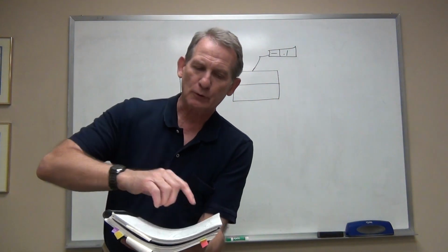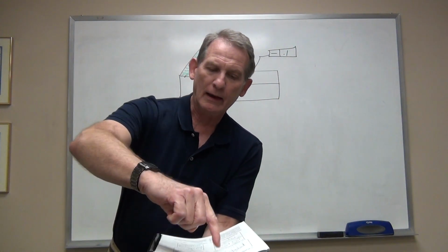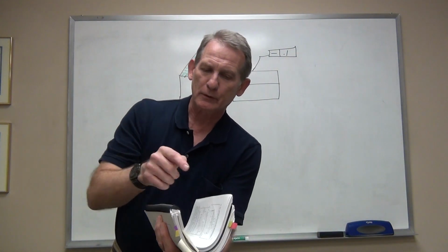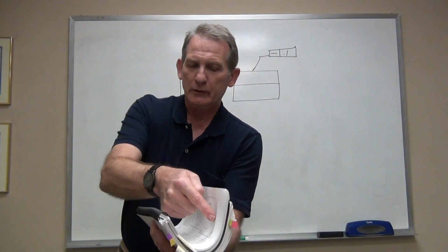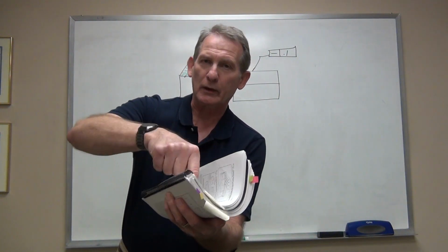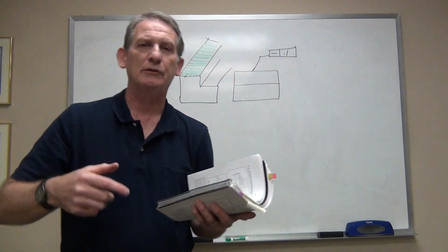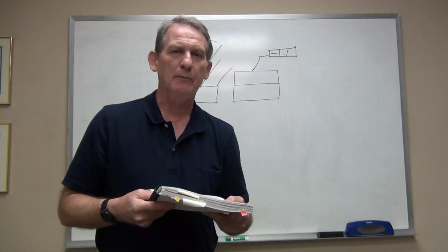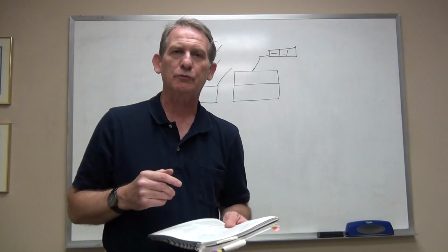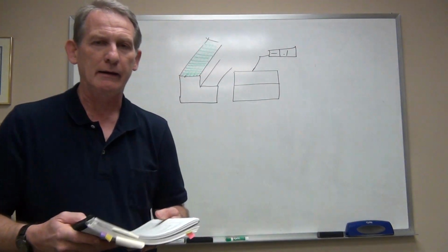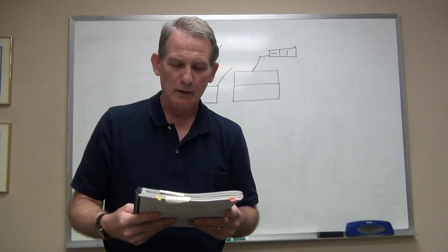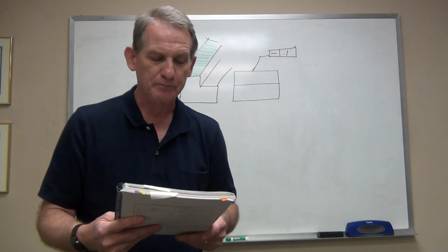So in this direction, I have very good straightness. Let me curl it up here a little bit better. I have good linear straightness here. Obviously in this direction, I don't have good linear straightness. So that's an instance where you would have two different controls for that surface. It's really, I guess you would call it, a cupping or a curling control for that straightness.